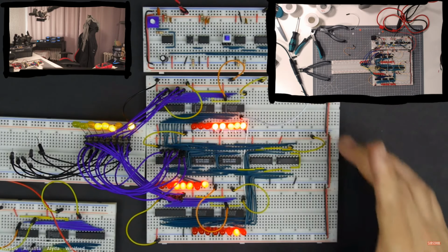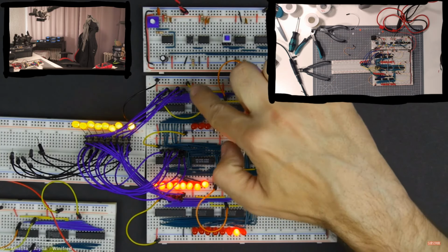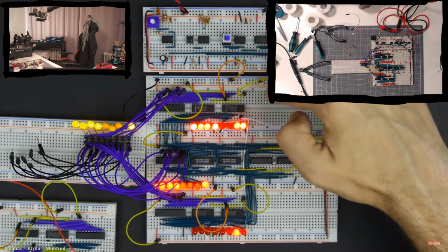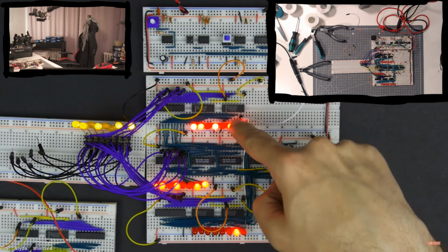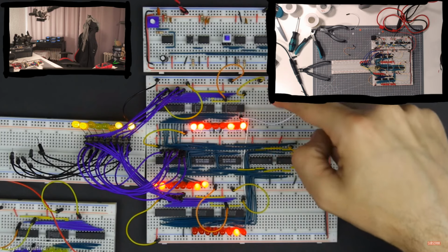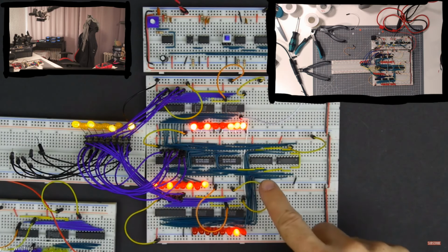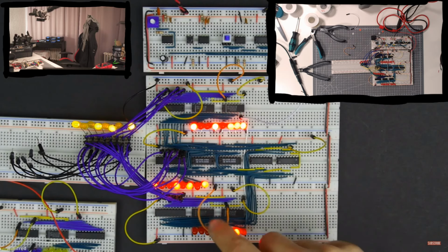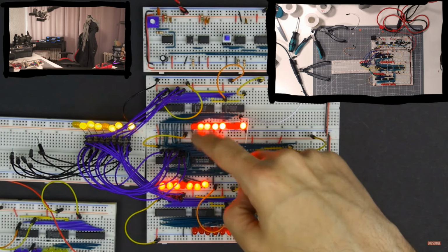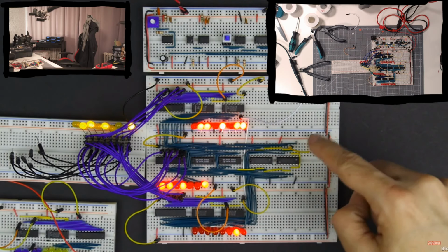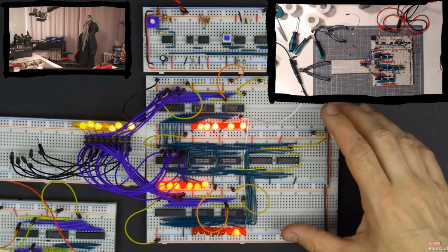And so I think that pretty much does it for our ALU. So we've got our A register, and we have our A out and A in signals that we can bring high or low to turn on the A in or A out signal to read or write from the bus. We also have a clear signal here if we want to just clear it. And then we have our B register with the B out and B in signals that we can set, and then of course a way to clear the B register. And then we have our ALU, which has an out signal, which outputs the contents to the bus. And then we also have this add or subtract bit. And so that pretty much does it.